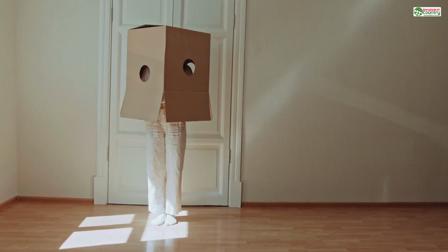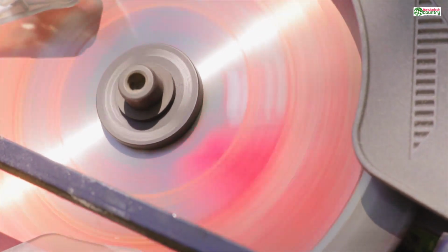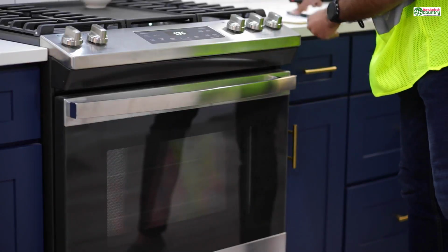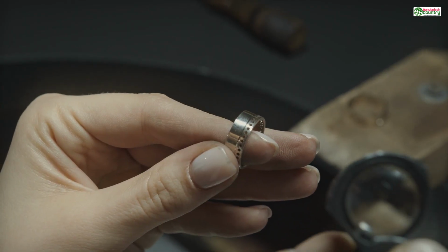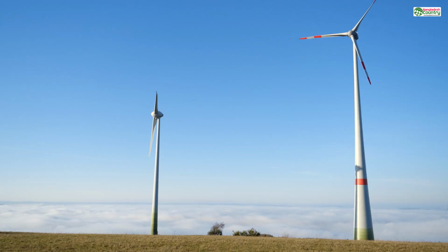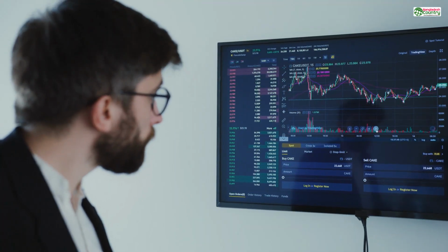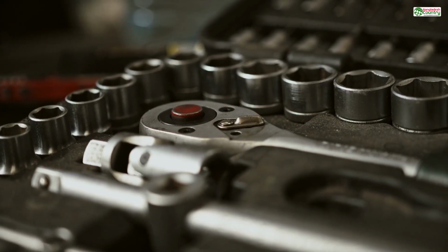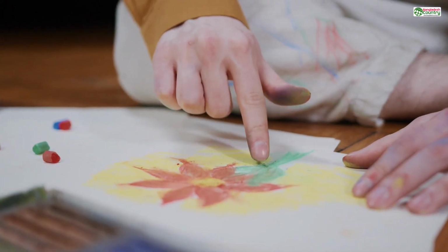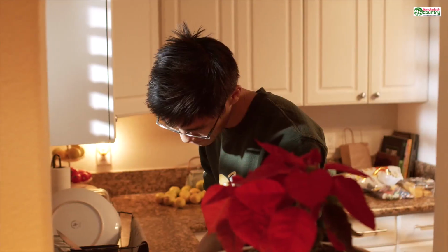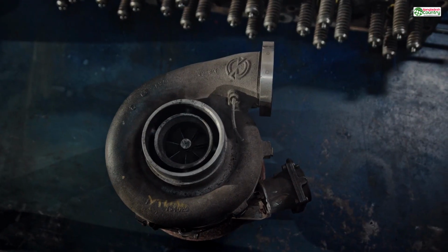You can drag this cutting plane through your entire model and visually inspect every single wall to make sure it looks robust. A powerful free tool that everyone should know about is Mesh Mixer. You can import your model and use its thickness analysis. This tool is brilliant. It creates a color heat map of your entire object, showing you the thinnest parts in red and the thickest parts in blue. You can see at a glance where your problem spots are.